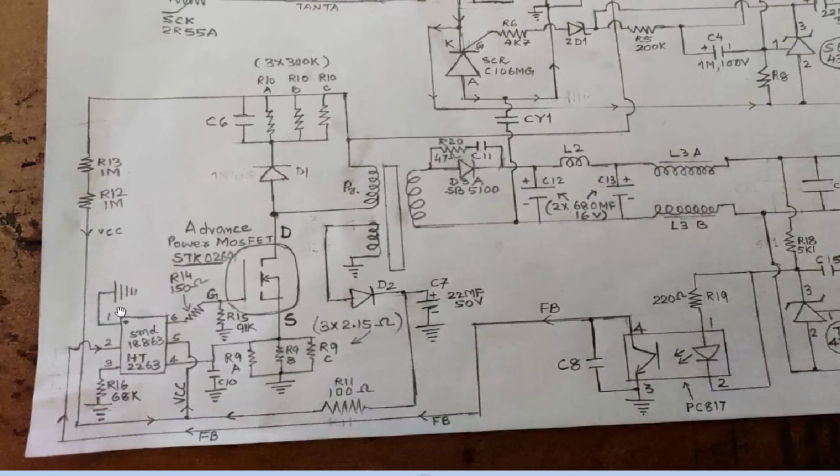Next we have here the IC. If it receives ground and receives VCC, you have to check pin number 1 and 5. If we have voltage here, this IC should start. At that time, if it is not starting, you have to check these resistors. This 0.7 ohm resistor acts as a jumper resistor; only a very limited voltage will be dropped on it. You have to check the resistors in off condition, these resistors and these resistors, and you have to check the feedback circuit.